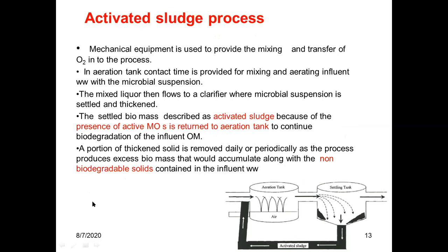Mechanical equipment is used to provide mixing and transfer of oxygen into the process. In the aeration tank, contact time is provided for mixing and aerating influent wastewater with the microbial suspension. The mixed liquor then flows to a clarifier where the microbial suspension is settled and thickened.